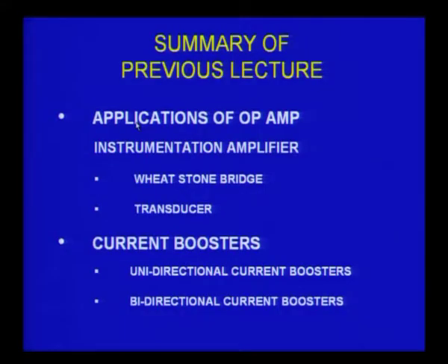You might recall, as you see on the screen, we discussed the applications of operational amplifiers, especially the instrumentation amplifier configuration, how it can be used for amplifying the signal from a Wheatstone bridge, and we also discussed how in a Wheatstone bridge you can have a transducer or a resistance sensor connected in the form of a bridge, used along with the instrumentation amplifier, so that you will be able to measure different parameters like the strain or the temperature, etc.